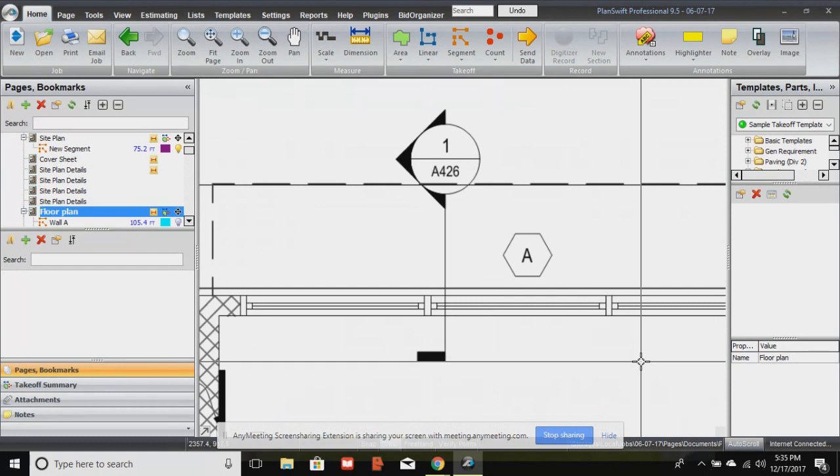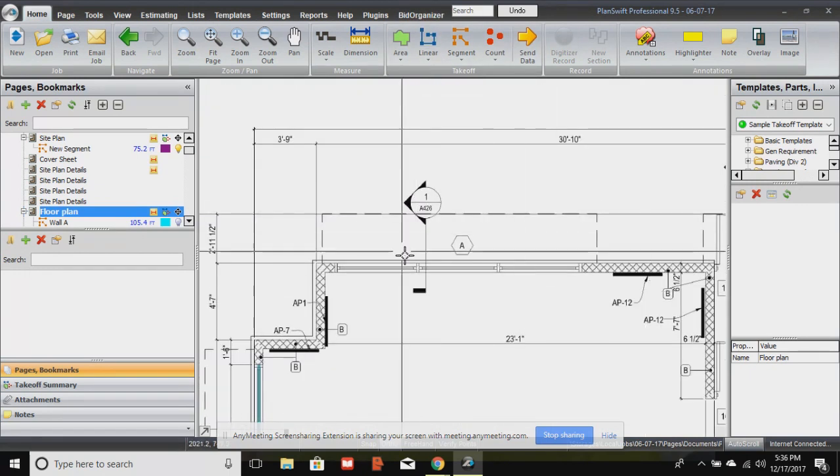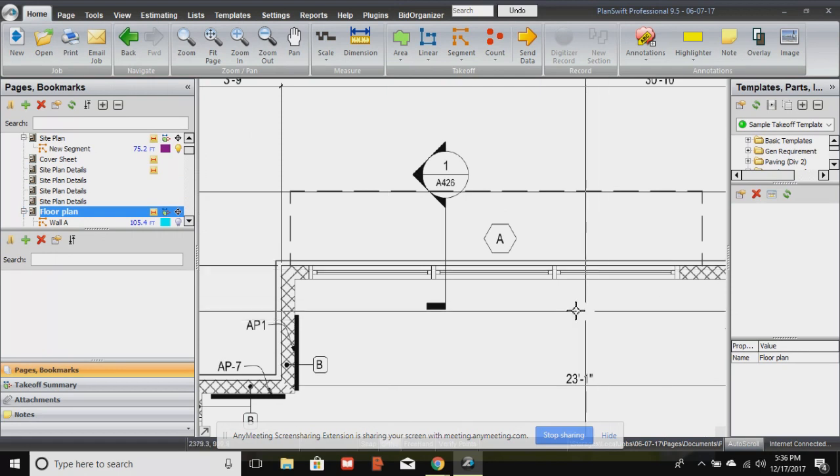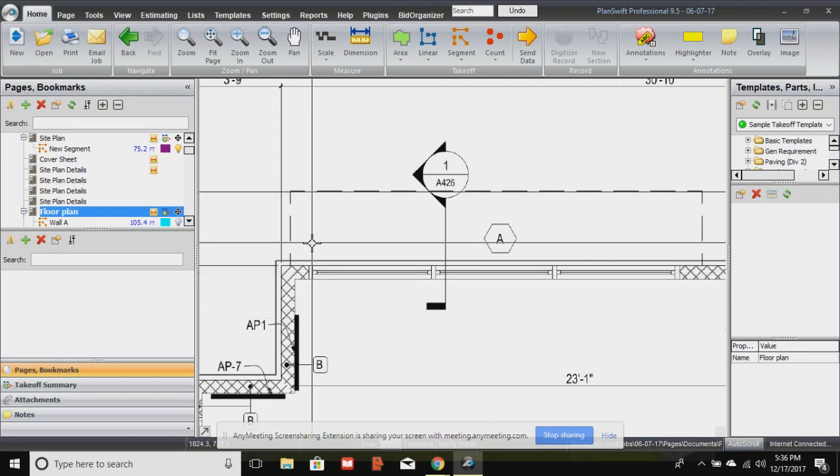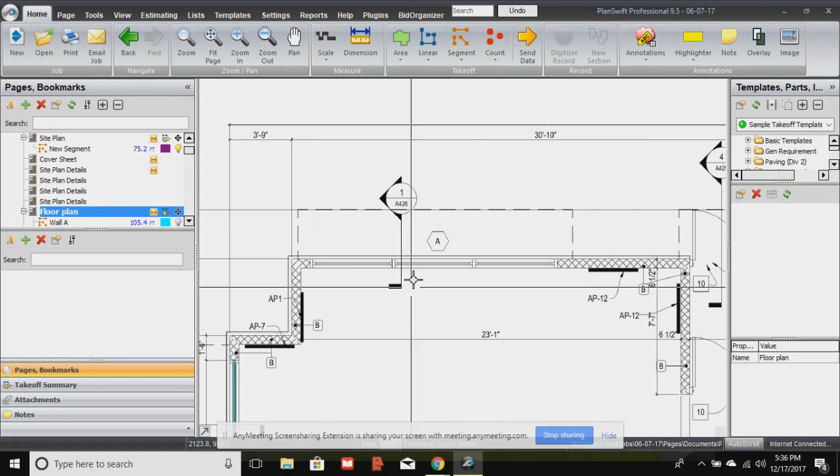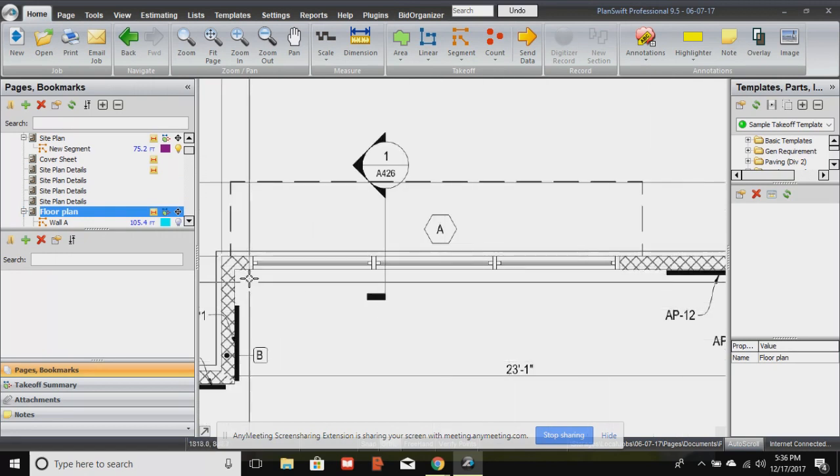Second view is our section view. Okay, and this is a section view marker. Remember what it looks like: a little circle with a triangle hat, points to one direction or the other, and has that long little, what I call its leg, and then a little foot, right? And wherever that leg is going through, that section view marker is referencing that section. Remember, a set of construction documents is a graphical representation. And so after you get used to what you're looking at, what this is trying to represent is a 3-pane window.